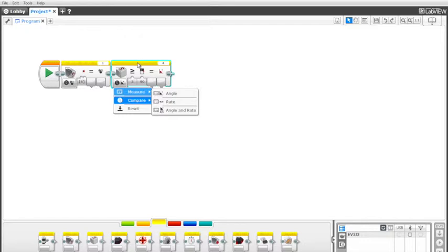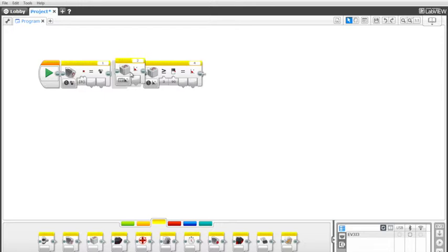And one special thing about this gyro sensor is it allows you to reset, because gyro measures angle, right? The angle keeps changing, and depending on where you started, if it increases by 90 degrees, for example, it will be added on top of your initial angle. So you always want to reset the gyro sensor angle to be 0 before you make use of the angle. So you reset to 0, then after the gyro sensor changes to 90 degrees, you can reliably use the end angle.